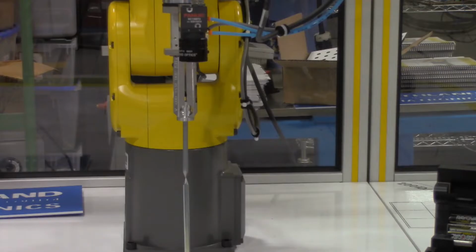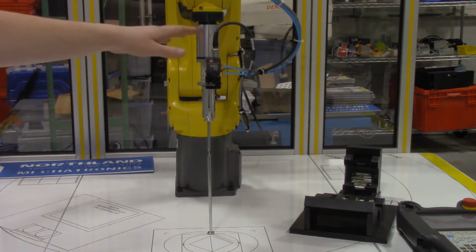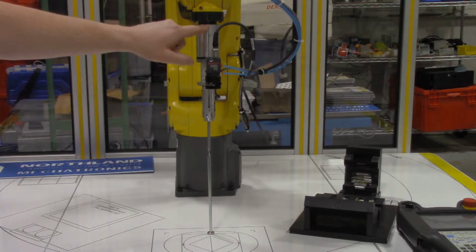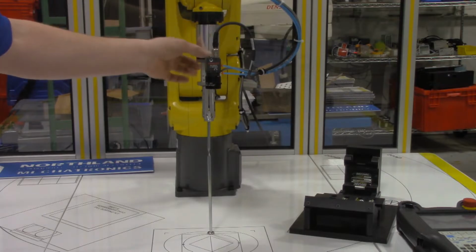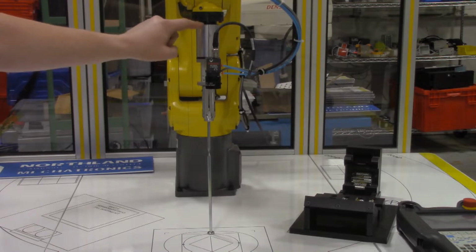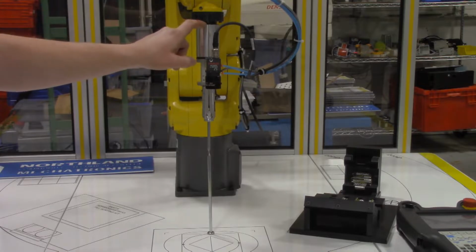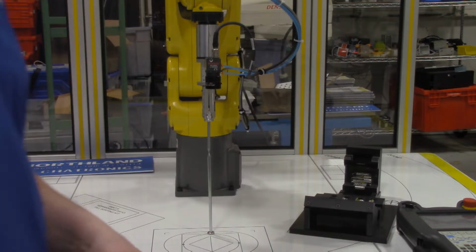So let's take a look at the robot itself, and I'm going to zoom out a little bit. Wrong way. Okay. So by default, the end of arm tooling is the end of the tooling center plate. So here we've got a piece of aluminum that's been machined that the gripper is bolted onto in this case. And technically, by default, the end of arm tooling is right at that center point, right there, without us doing anything else. And I could actually demonstrate what that looks like.